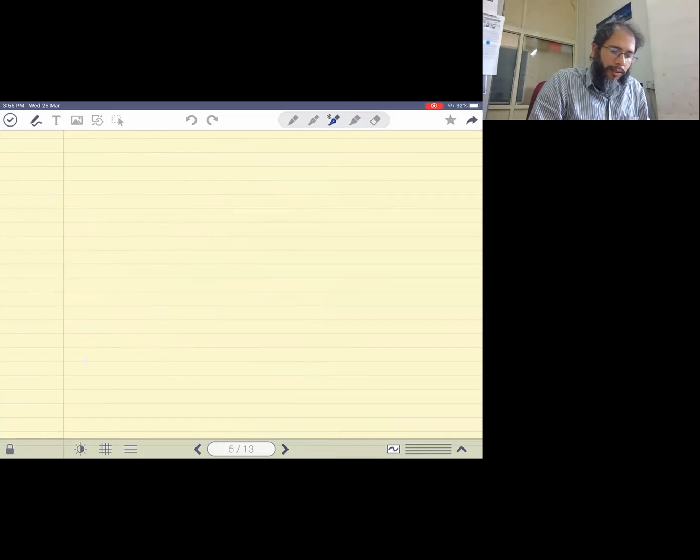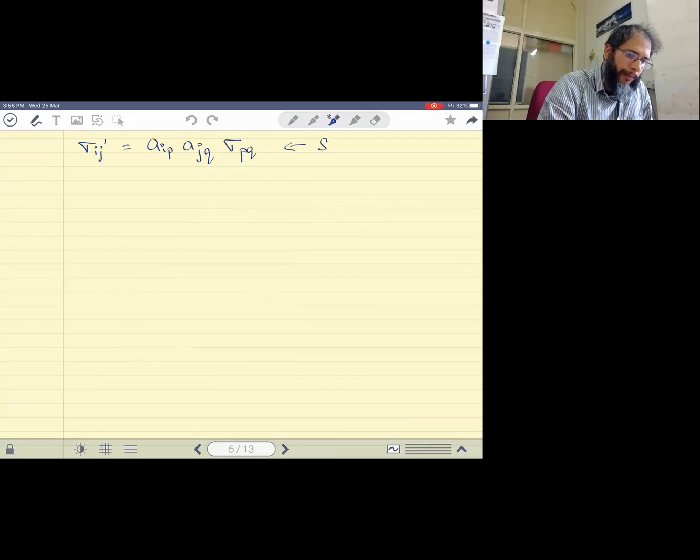Now, if you go back, we do a quick recap. We learned that sigma ij prime is nothing but a_ip, a_jq, and sigma pq. Okay, so that was the stress transformation rule, or in fact, I should write the tensor transformation rule.